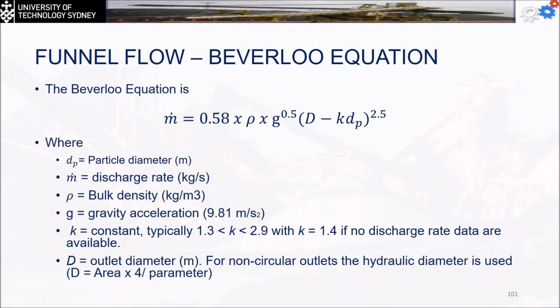Now you know what the hydraulic diameter is, right? How many of you did air conditioning before? How many of you are doing air conditioning now? Good. Usually when you do the design for ducts, you calculate the diameter, so that the duct is not circular.